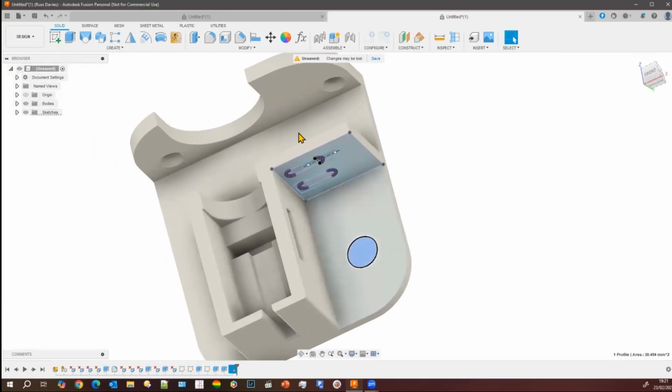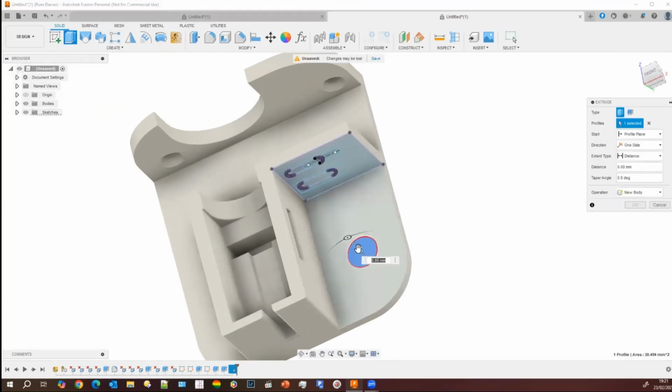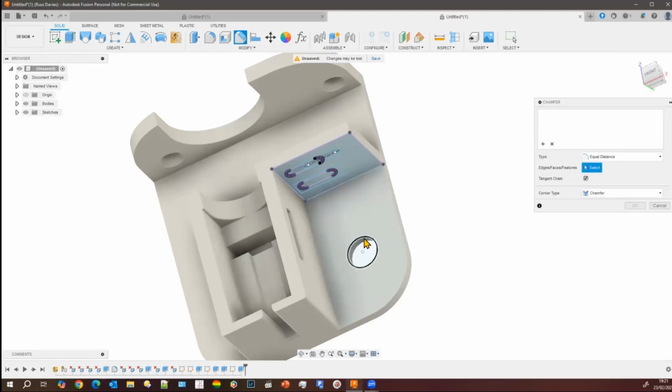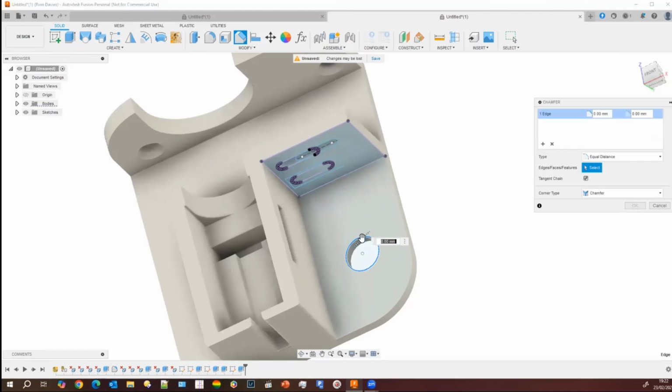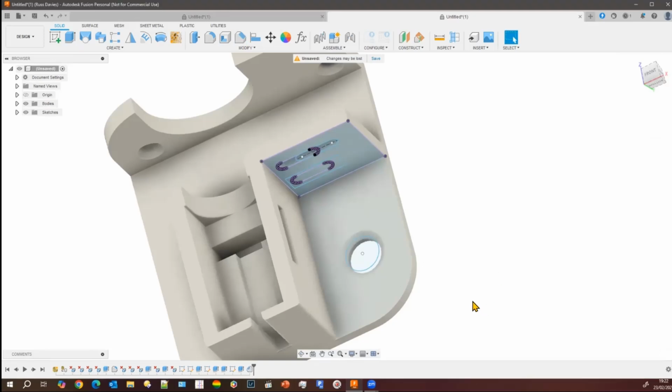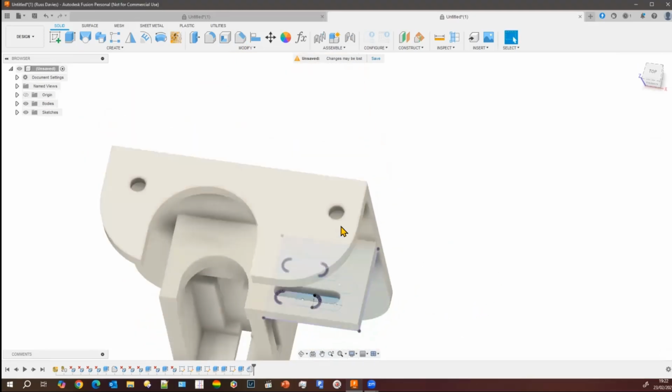sketches on, highlight it, push it through, put a taper on it, in the same way you can make these smaller or bigger. In the same way I've done the slot, you can go on there, create another sketch by projecting the face onto your sketch plane, and then either filling the hole in and making a new one, or putting, if you like, a sort of bush in there which will fill it in.